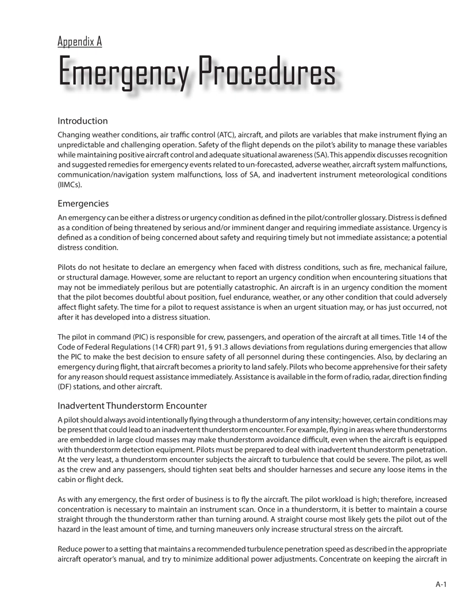The pilot in command, PIC, is responsible for crew, passengers, and operation of the aircraft at all times. Title 14 of the Code of Federal Regulations, 14 CFR, Part 91, Section 91.3 allows deviations from regulations during emergencies that allow the PIC to make the best decision to ensure safety of all personnel during these contingencies. Also, by declaring an emergency during flight, that aircraft becomes a priority to land safely. Pilots who become apprehensive for their safety for any reason should request assistance immediately. Assistance is available in the form of radio, radar, direction finding, DF, stations, and other aircraft.